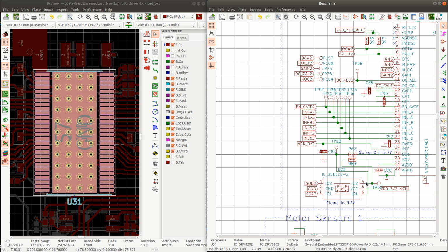since the current sensing, in this case, is part of the DRV chip. So current sensing in this case depends on the DC cal value that we read when we set the DC cal to high, and the values that we read here as 0 points. So we need to put this code in the driver that is responsible for the DRV chip, because we need to be able to calibrate the readings on these pins.